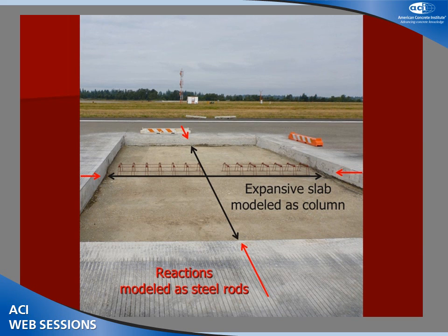So drawing an analogy back from the test scenario to the in situ field scenario that's being modeled, the expansive slab that would be cast in this space is now modeled as a column, 4-inch diameter, and the reactions from mature concrete have now been modeled as steel rods.